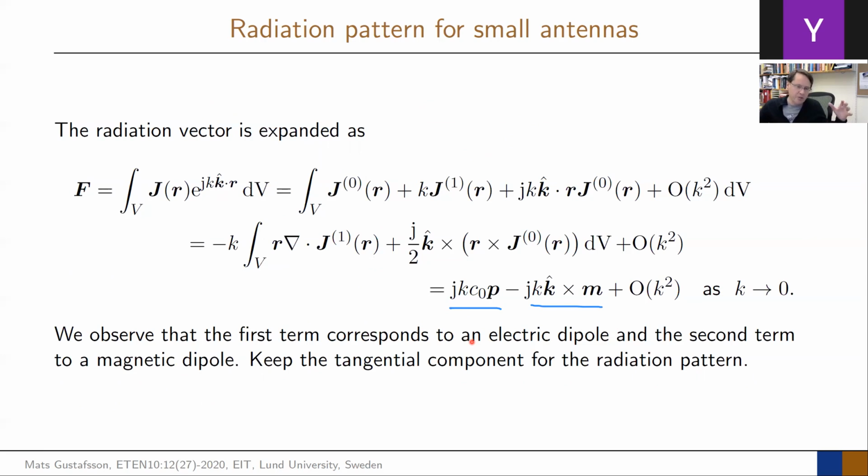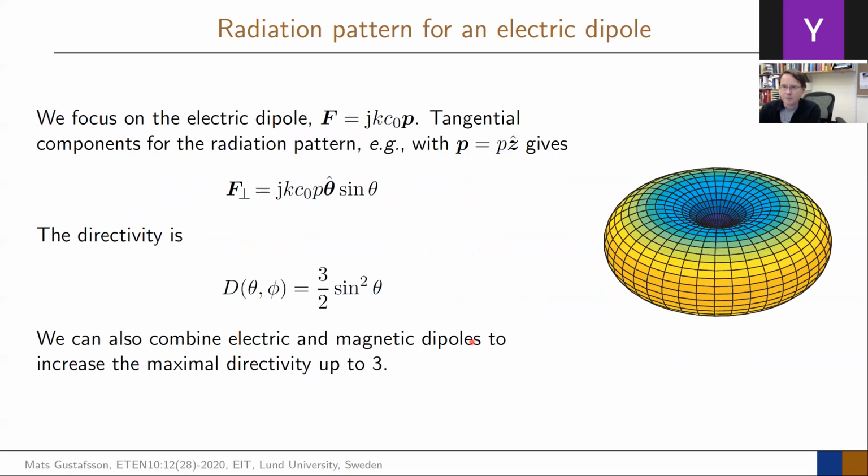And that really shows that fundamentally when you start shrinking this, it has to radiate like an electric dipole, you know, the regular donut you have, and superposition of that, some magnetic dipole that sits there, which is the same shape, but basically turned 90 degrees around. And then you can combine those two in any way you like. But everything that's small radiates like that. You cannot have some directed beam coming out from it. It's something very wide in every aspect in some ways. So really this donut type pattern comes out. So that is the radiation pattern that we will have.